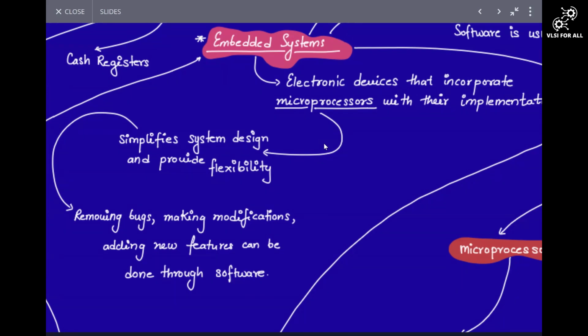You can simply design a finite state machine which switches the traffic lights based on a timer that you give or based on some inputs that you give. So we can design just an FSM in hardware and build a chip out of it. Why do we need a processor for this? Of course, that is the first thing you can come up with, the easiest thing, and the lowest cost thing, just direct hardware that you build and design a chip out of for that purpose.